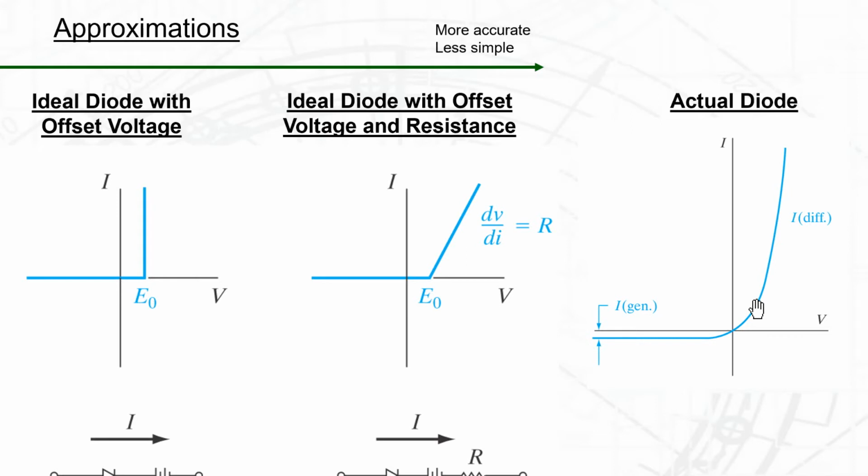Okay, I'll just say two things very briefly. The principle of superposition allows you to analyze a circuit. If the circuit contains all linear elements, the principle of superposition will allow you to look at the effect of multiple voltage sources, multiple current sources, and you can look at each one of them independently. It also allows you to simplify the circuits in ways that you can't do if you have nonlinear circuit elements.